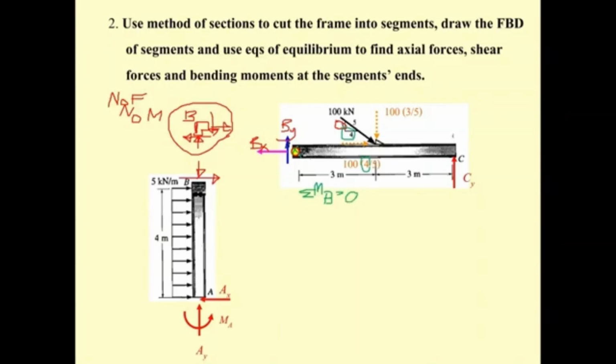And then the C sub y is going to rotate like this. Counterclockwise rotation is positive. So we have C sub y times the total of 6. And then the beam is usually assumed to have very small depth, so the inclined force will produce a very small moment and is negligible. So it's only the 60 times 5, this is going to be the 60 kilonewton.